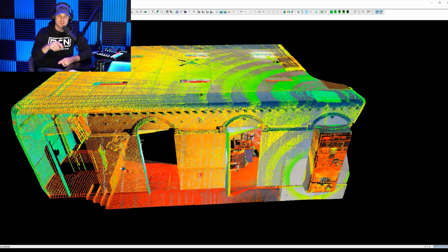As you dig into this more, I know there are some videos that show the inside versus the outside, and there are some areas where error compounds quite a bit. The biggest takeaway I've seen from some of the Matterport data, even when I did the iPhone tests, is that it can come out good, but it also can come out pretty bad. It feels like it's not quite as consistent or reliable, and it may really have to do with the environment and the feature types. But I think this does show quite a bit to those who haven't done any comparison: it's pretty decent, but there are things to keep in mind when using it for actual measurements.